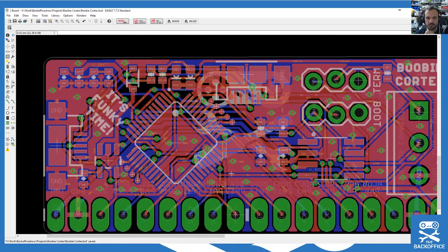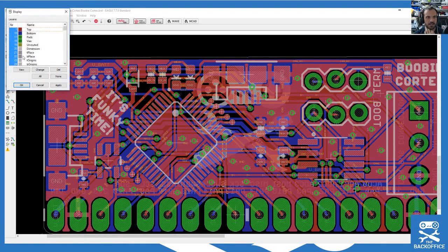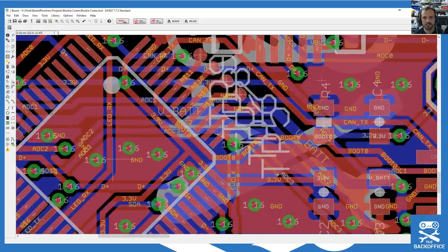So the reason you've got to be so cautious with this is because when you've basically done it and you send it to those PCB places, depending on how messed up their engineer is, they might just print it exactly as you've got it, and you'll be really disappointed because it'll be mental. Right, so I've just turned on the T names and B names. You can see those TP things here.